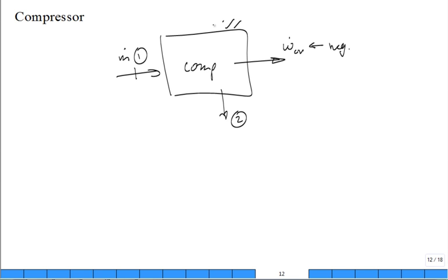Compressors often are not good heat exchangers. They may not insulate a compressor to prevent any heat transfer from it, but often we just assume it's negligible. Again, that's a difference of opinion. Okay, think about it. I have a steam turbine. I'm trying to get all of that energy out of the flowing steam and convert as much as possible to useful shaft work. If I have any going to the room or surroundings, that's going to be a loss. I want to avoid it.